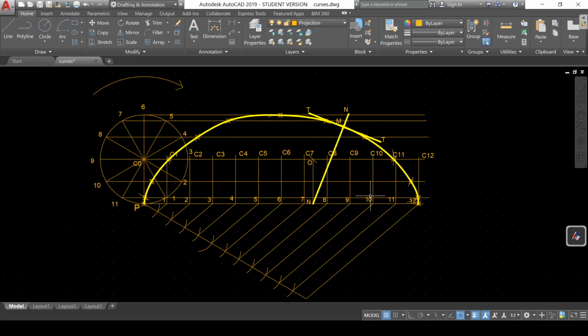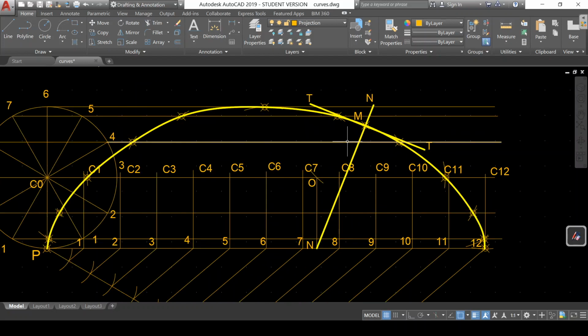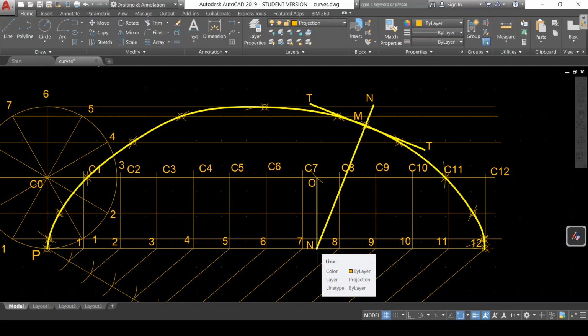The point we were supposed to choose, we have chosen it here. Anywhere if we choose the point, the procedure is like this. From the point, take a radius in the compass, cut on the center locus line, and you will get the location of the center. So let us say that this is the location now for this point M. Then draw a vertical line from that new center till the base line, that is the fixed straight line. That intersection point is N. Join that point to the given point, extend it.